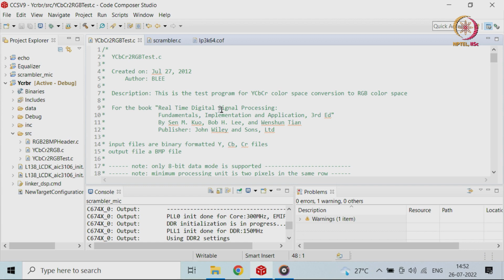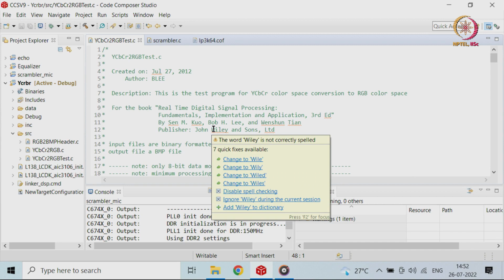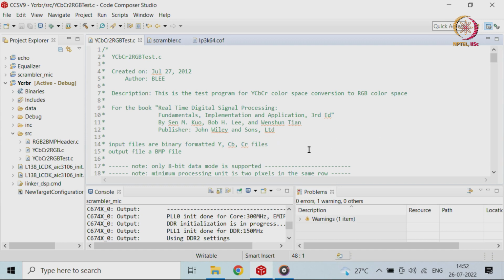If the code is written in C, how you can reuse it on other boards also with little modification, is what I want to show. In the DCT part, as we said, there was assembly code, so one has to modify it, because that was meant for this board, and to make it work on the 6x board you have to modify all the assembly instructions.